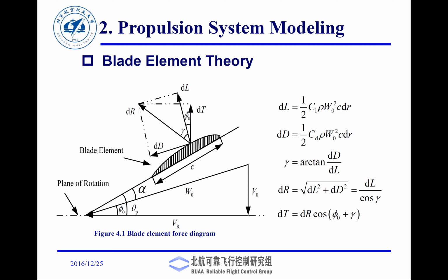It's called dynamic pressure because this moving air comes in contact with this fixed surface, stationary relative to the moving air. This surface could be moving, but it is stationary relative to the incoming air. So this differential velocity, or differential kinetic energy, gets converted to pressure.